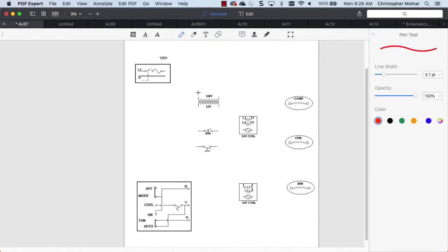Okay, so then we have our transformer, we have a compressor, we have a CFM, condenser fan motor, we have an evaporator fan motor. In this case, everything is a shaded pole motor. In real life, will we see a shaded pole motor for this? No. We're going to see PSC motors or a CSCR on this stuff. Okay, we have two pressure switches now. Pressure switches are not operating controls. They are safety devices. So we'll have to make sure those get in the circuit.